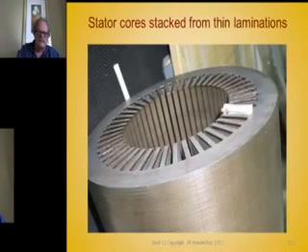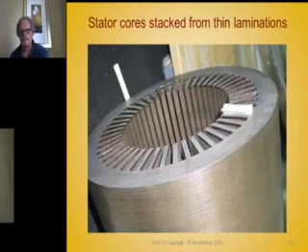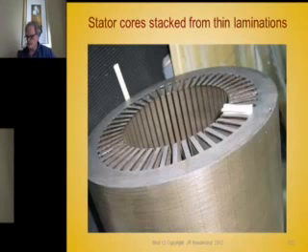This is a picture of a core that I showed on the last one, a close-up view. This one is stacked and bonded. Now I'm going to show you some pictures of a finger plate on the end of a stack. This is a case where, in retrospect, I should have used a finger plate, because these teeth are very long. And yeah, they're bonded, but as it turned out, the bonding didn't take on all the teeth on the ends, and some of these actually stuck up a bit.